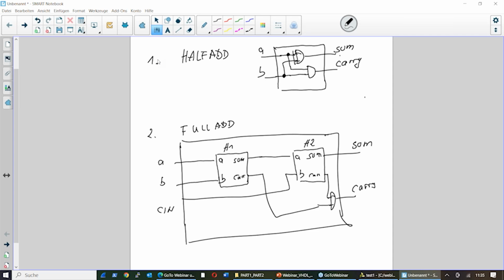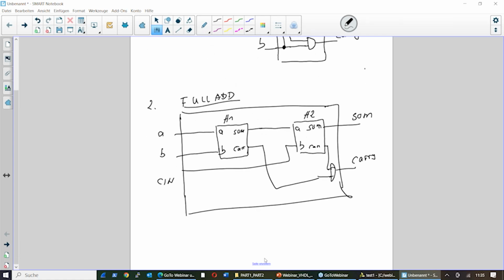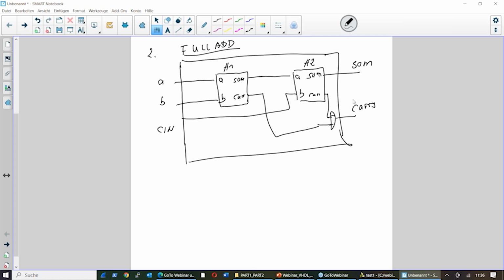That's the theory, okay? So now I have a very nice element called full add, which can now be combined together to define an n-bit adder. For example, now I would be able to define this adder if I would like to do this, okay? So for example, maybe first a simple one, let's say a 2-bit and 2-bit, okay? A and B vector, and the output would be 3 bits. How would it look?